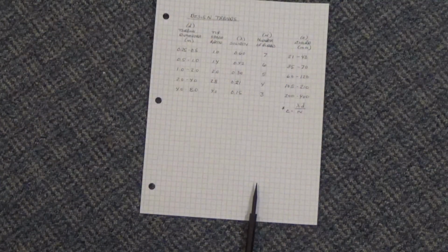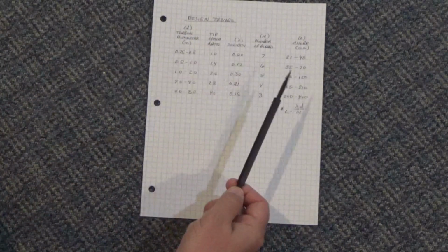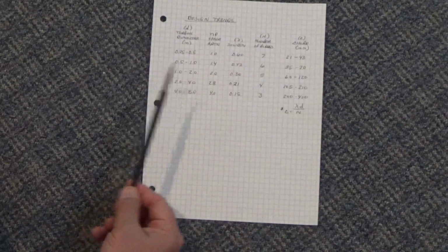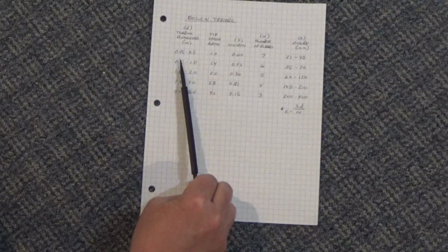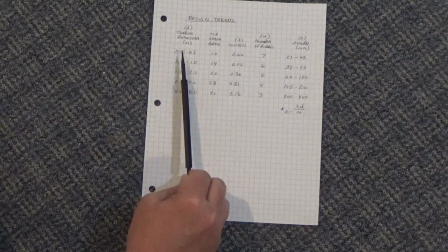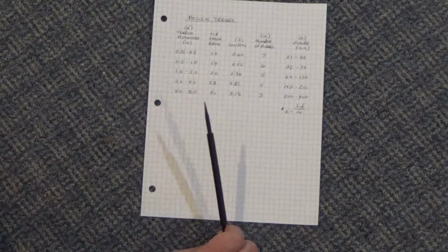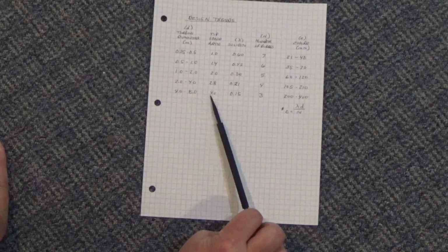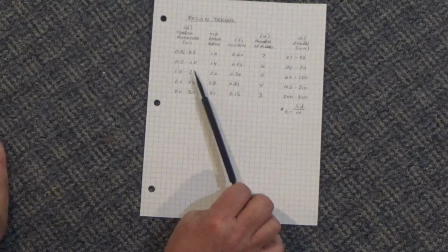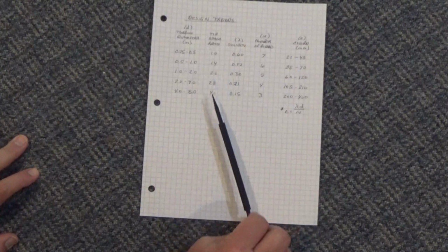So anyhow, I made a table. This is just some thoughts. It's not anything very scientific, but it's hopefully a guideline or just looking at some design ideas. What I did was I put the turbines in various size categories, like 0.25, 0.5. I just doubled them, 1, 2, 4, so doubling the size every time. And the big ones would probably have a tip speed ratio around 4, little ones around 1. Ones that I'm used to working with probably around 2, so you probably want to run at those speeds.